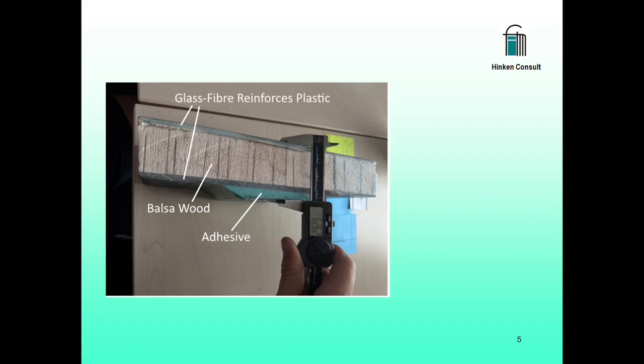Special challenges, however, are the need to detect rather small air voids and to suppress parasitic signals which are generated in this natural and therefore inhomogeneous balsa layer on the path of the microwave rays forth and back.